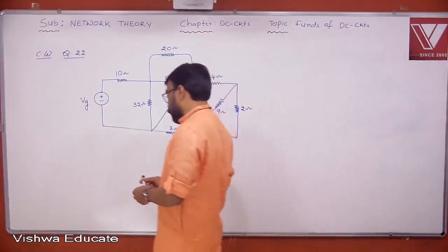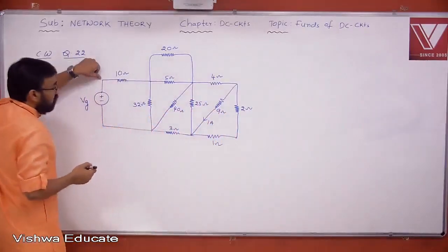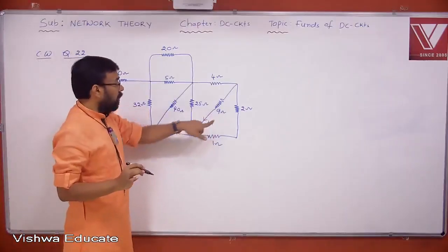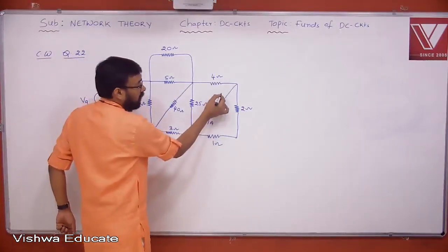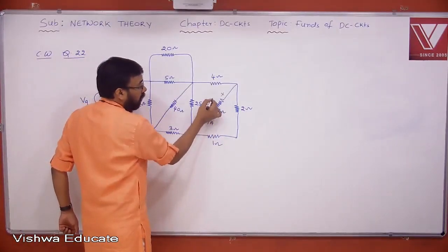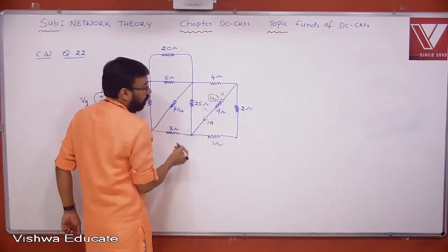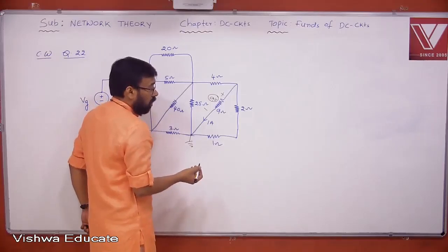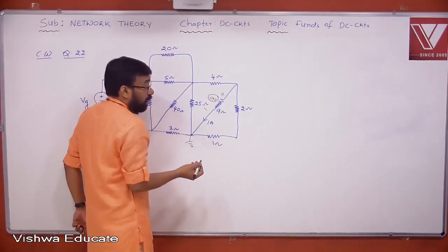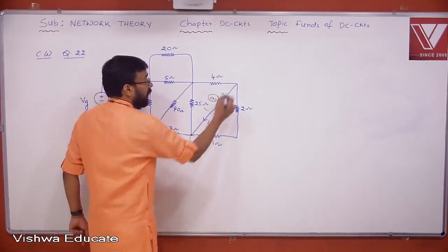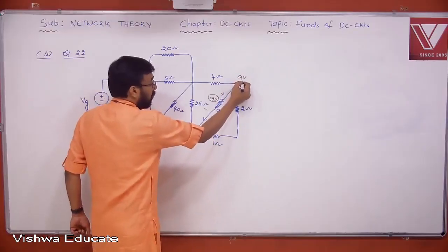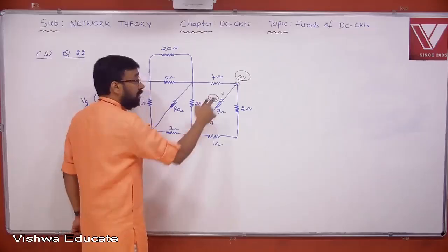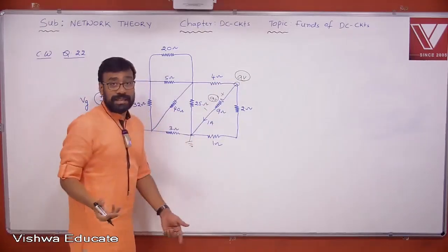Okay? Look at this. To get this voltage, you require one node voltage somewhere. Further, the data is given that 9 ohm and 1 ampere is given. What is the voltage here? 9 into 1, you got 9 volts. Yes or no? If you take this one as 0, definitely, otherwise there is no point or meaning, it doesn't make any sense. Most people simply say that this is 9 volts, without bothering about whether it is 0 or not. But I'm telling you, without taking 0, putting it 9 volts doesn't make any sense.